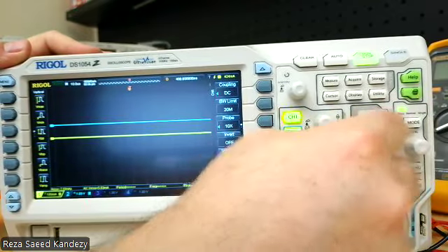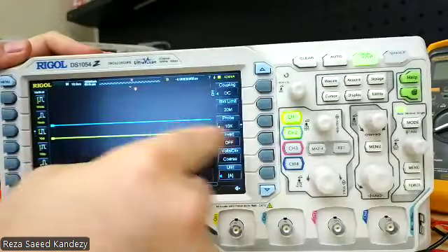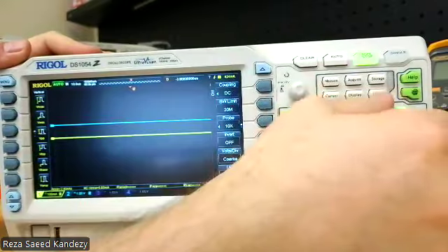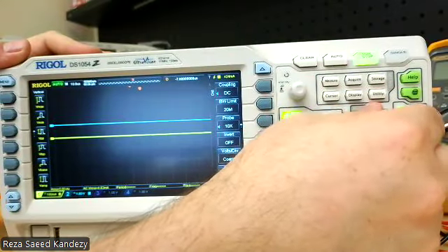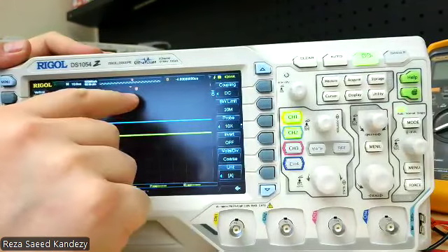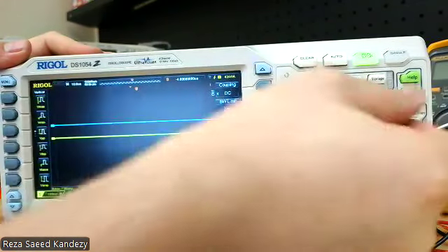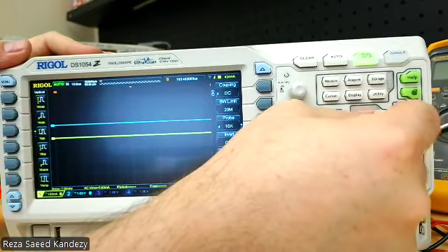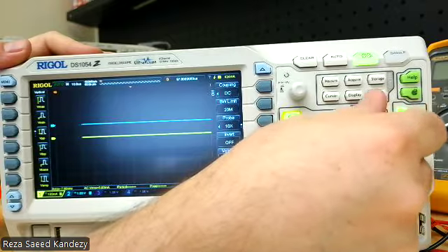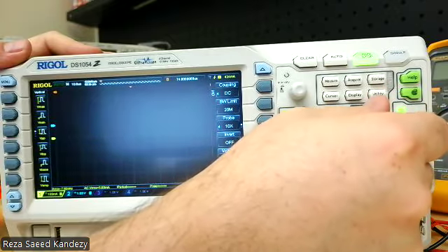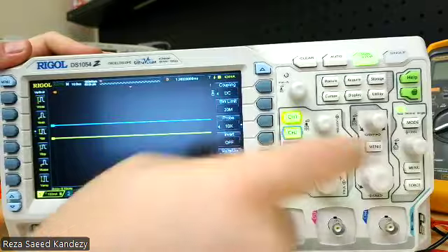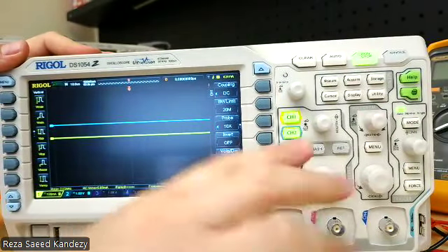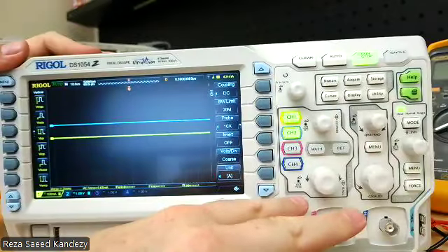And this knob, you can see that because it's a flat zero, but it would shift your waveform right and left in time. You can see this indicator that is moving left and right. So basically we are changing the position of our system. And again, if you push it, it would reset to zero. Okay, so this is what we have so far.